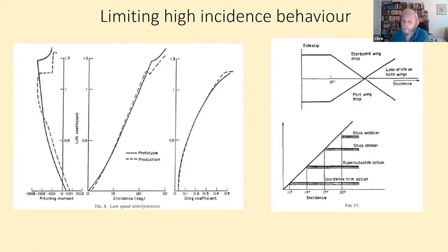So we had to install angle of attack protection, if you like, which meant that above 17 degrees, we started to get a stick shake. And if you got up to about full 20 degrees, then you actually got a full-blooded wobble on the stick. The reason it was a wobbler was because André Toucard, the French chief test pilot, flatly refused to have anything at all to do with the stick pusher. But nevertheless, Concorde does have some sort of stall protection in that respect.